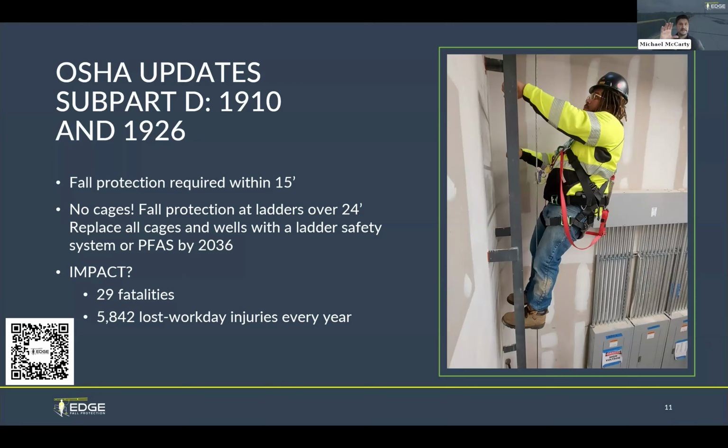I'm just going to cover the biggest things that impact roof safety. There was a lot of miscommunication or non-clear standards about when you need fall protection up on the rooftop. They cleared that up and said anytime you're within 15 feet of the leading edge performing work, you need to have fall protection. Pretty cut and simple, pretty plain and dry.